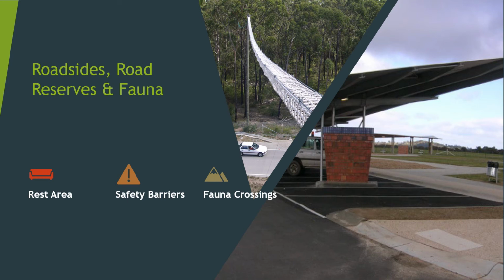This is due to the steep sections involved here where we don't want traffic leaving the road, and then using a wire rope style along the embankment itself to ensure that any views aren't inhibited from the steel beam type of guardrail.